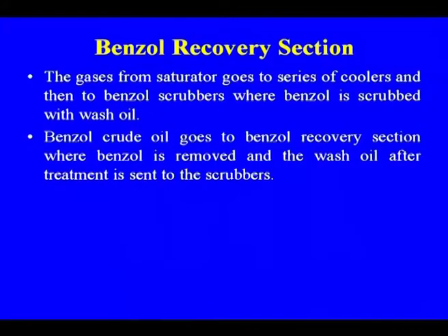Benzol recovery, because this is one of the very important parts in the coke oven plant, where we are recovering the aromatics. The gases from the saturator go to a series of coolers and then to the Benzol scrubber, where Benzol is scrubbed with the wash oil. Benzol crude oil goes to the Benzol recovery